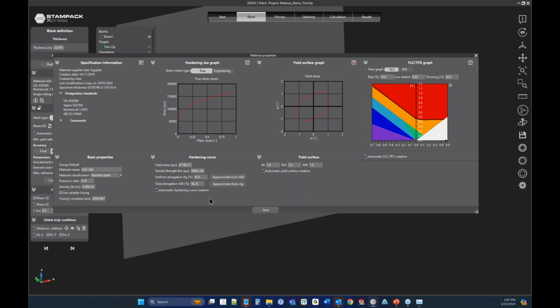Okay, good. How about limitations for part size or material thickness? Are there any limits there? So, size. We have customers that have parts with thickness 0.01 millimeter. This is a Swiss company that makes parts for watches, so extremely high precision stamping, and the thickest part we ever simulated was 18 millimeters. Let's say the standard stuff goes up to 8 millimeter or 10 millimeter, I would say. This is everyday business.